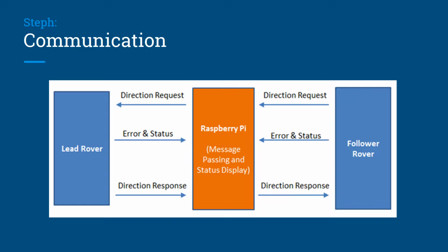The server was run overnight multiple times with simulated direction responses and motor commands. During these runs, the intersection number and 8-bit value correctly incremented from 1 to 255. It was incremented when a direction request and direction response were successfully sent and received for each intersection.